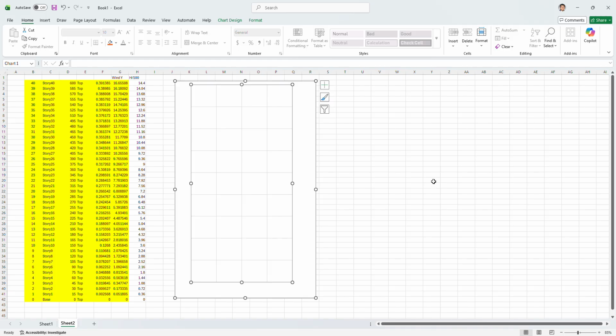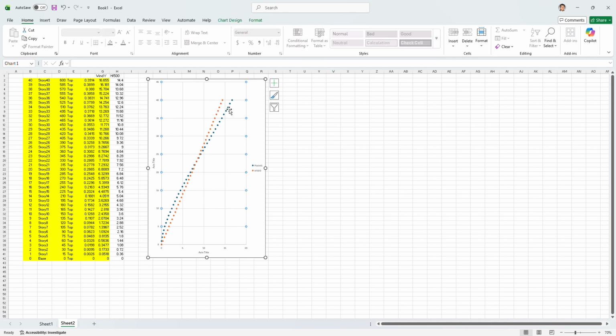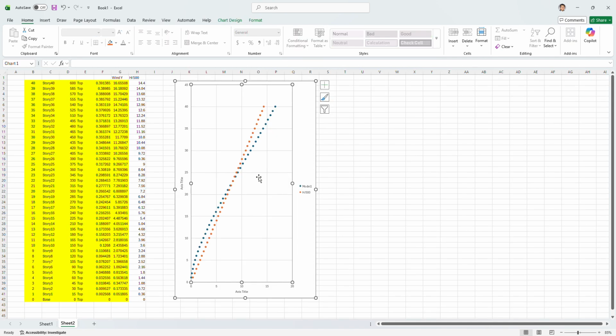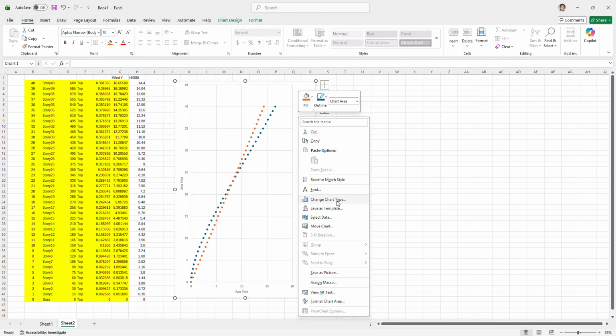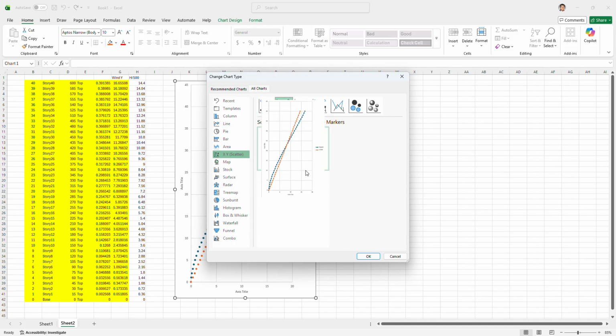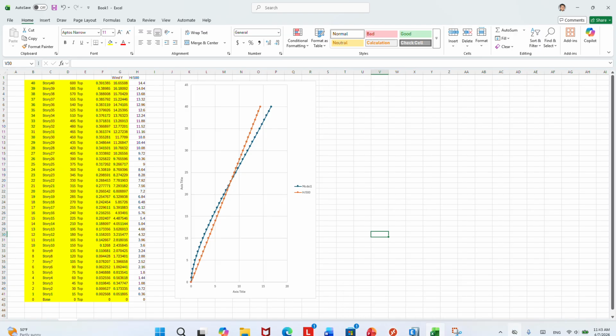So 500. So I think upper portion we still have an issue with the deflection criteria. Let me change the chart type with the line. All right. Right. This example, I have guidelines is H over 500, but my deflection curve here has exceeded. So this one still is not good. We need to stiffen up a little bit.